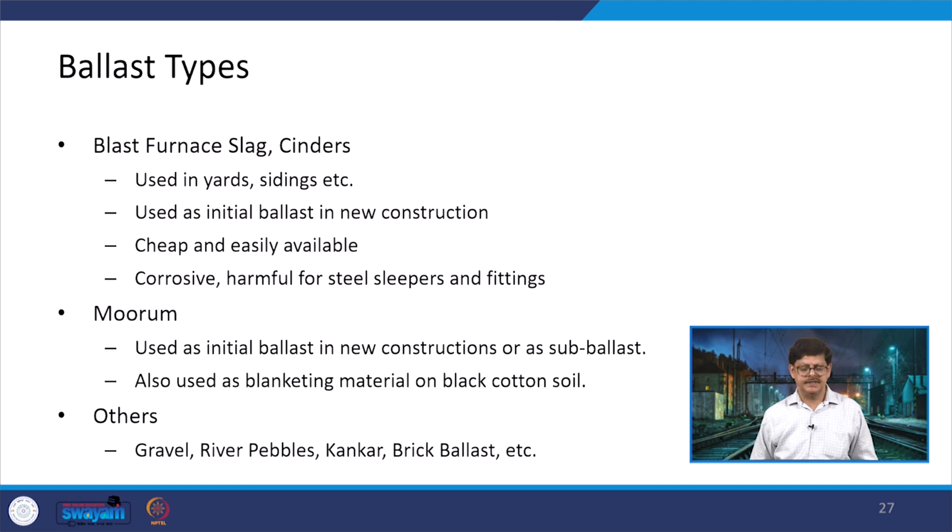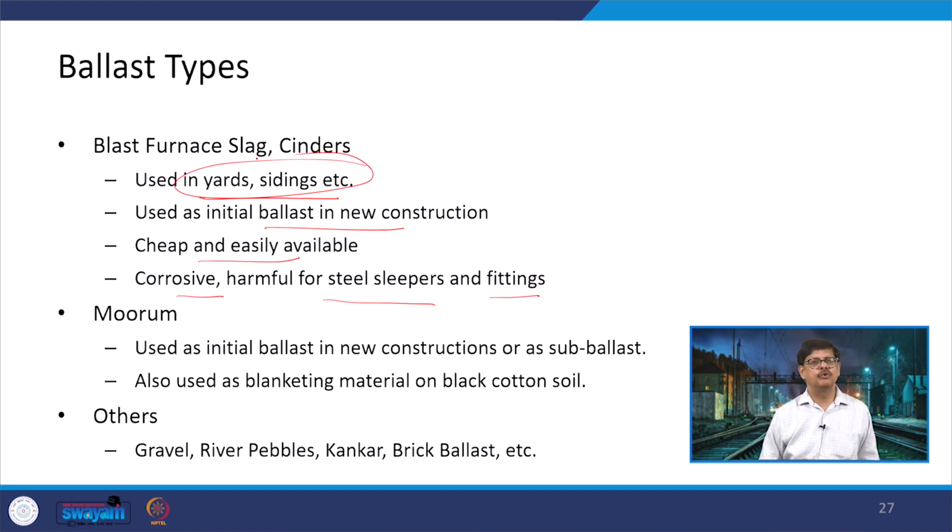It can be blast furnace slag or cinders, but they are usually used in the yards and sidings. They are used as initial ballast in new construction, and then finally they are converted into broken stones. They are cheap and easily available, but they are corrosive, harmful for steel sleepers, and harmful for the fittings also. That is the reason we mainly use them in yards and sidings.